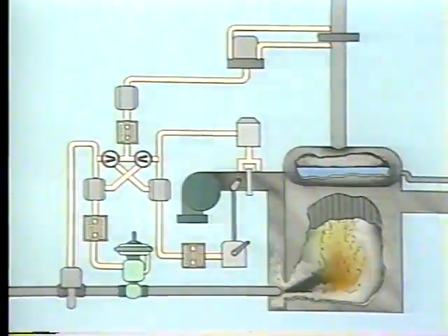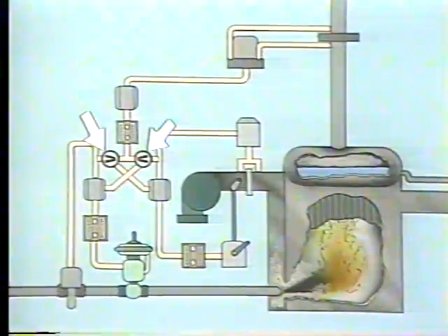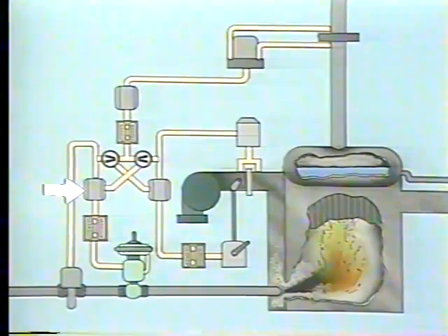Now that we have some background on auctioneering control, let's relate these concepts to the combustion control system. We'll add the feature of auctioneering control to the existing control system and see how it works. For this system, auctioneering control is provided by the addition of these two relays. The addition of two relays is sufficient because there's already a controller for the fuel flow system and one for the airflow system, so additional controllers are not necessary.